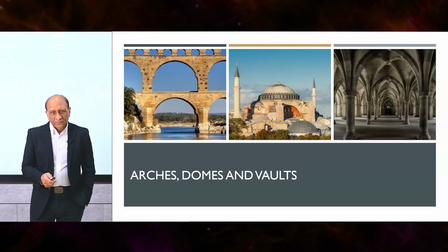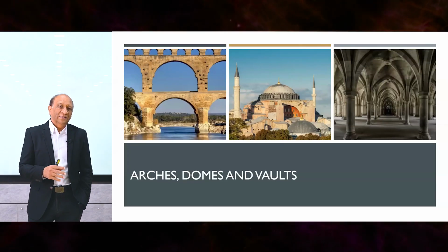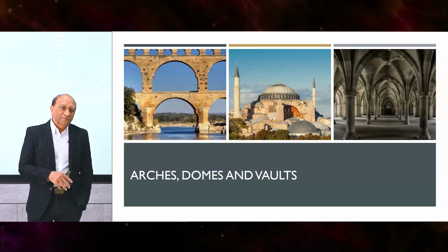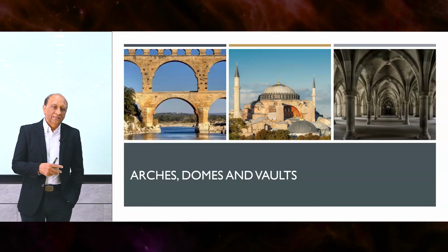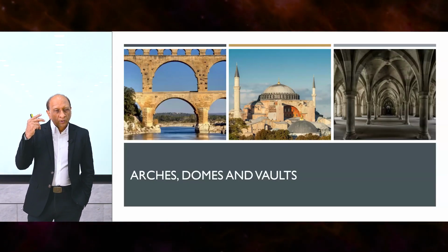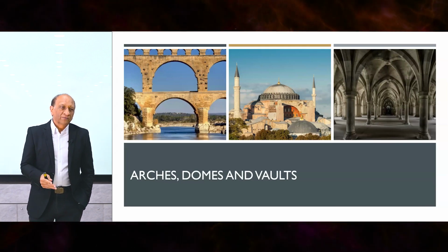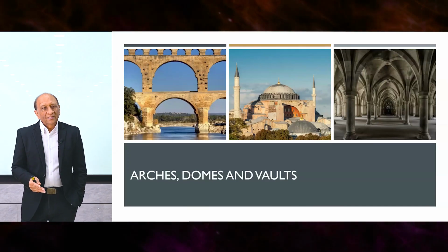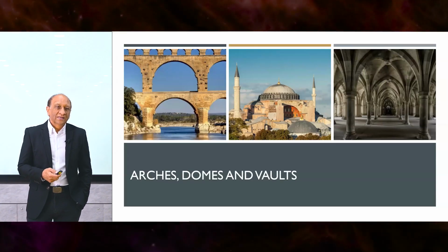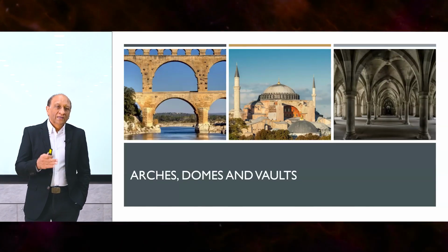and tie. So if you look at the old structures, historical, most of the structures you will find that they have a common feature, which is either an arch or a dome or vaults. And all of these are based on the concept of the thrust flow into the structure in such a way that the load applied to a structure flows through the structure within the structure's boundaries, goes to the foundations. And that has been always the way that the ancient architects, you can call them designers, engineers, or builders, have worked. And they took great effort in ensuring that the force flow is within the structure.